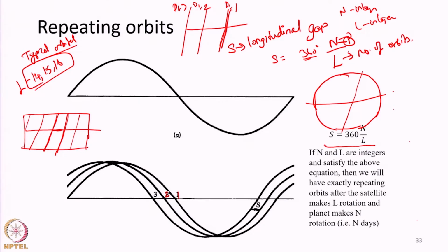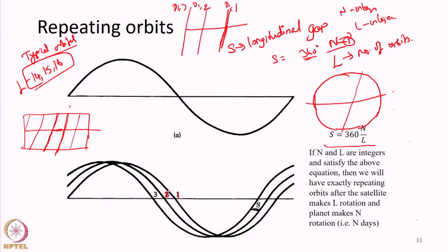Normally, the time period of our near polar sun synchronous orbit satellites will be roughly around 90 to 110 minutes to complete one full orbit. Earth would have moved at the equator by a distance of around 2000 to 2500 kilometers. Let us say this is orbit 1 day 1. When it completes one orbit and comes to its orbit 2 day 1, the shift in distance from its starting point A to B along the equator will be in the range of 2000 to 3000 kilometers. This is actually a large gap.